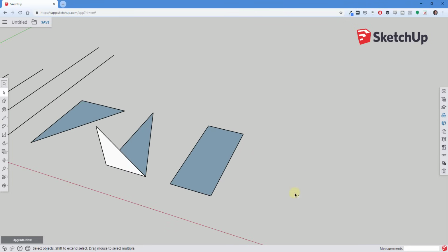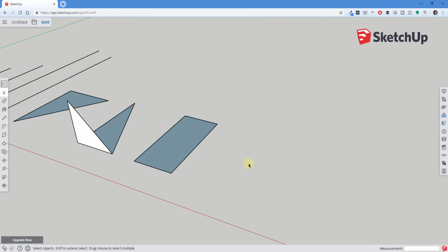And now I want to talk just a bit about these different colors that are showing up when we have tools active. Let's say, for example, that we activate the line tool by tapping the L key again. You can see if I start moving my mouse over different edges, I start getting these different shapes and colors, and dotted lines start showing up, and all those different things. Those are a part of SketchUp's inference engine. SketchUp's inference engine is where SketchUp tries to figure out where you want to draw different things. So it guesses where you want to draw, and it also gives you little tips.